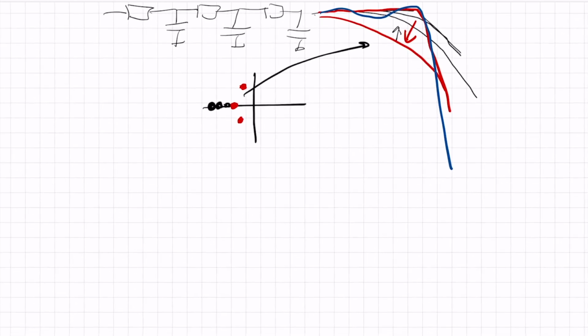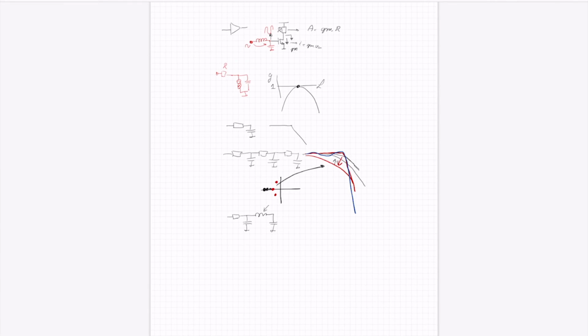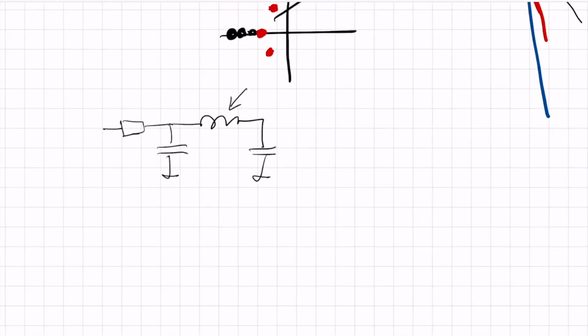And that's why there are more complex filters, and they were very popular in the 1930s, 40s. What people do is, okay, let's take the source impedance, take a first capacitor, inductor, and a capacitor, for example. This is a filter where you can make complex poles. But now we have introduced an inductor. And an inductor was good at these gigahertz high frequencies, but for megahertzes, these inductors become so big that you cannot put them on a chip. You have to put them outside, and yeah, that's not very practical. We like it all integrated.